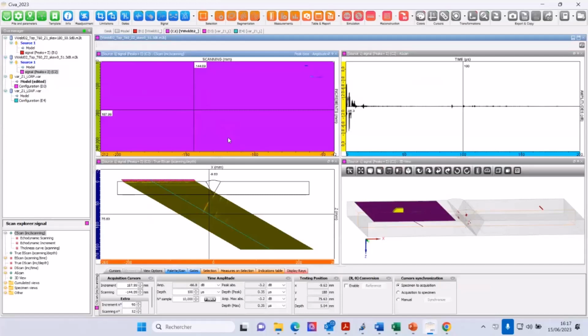The reason is, and you will see that just after, in the CIVA DS module you cannot directly load the full experimental data. You can just load binary files, and you need to export the experimental data and reload it in the CIVA DS. So the first step, and I will just show you in one case, not of course in the two experimental data, it would be a little bit too long, but the first step is to prepare the acquisition results thanks to CIVA Analysis.